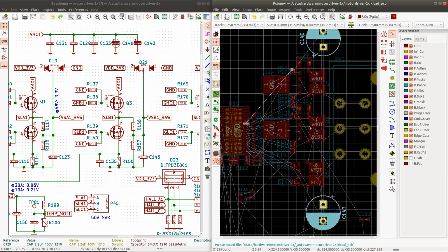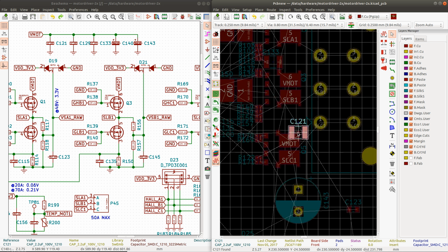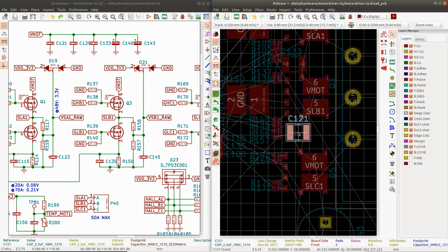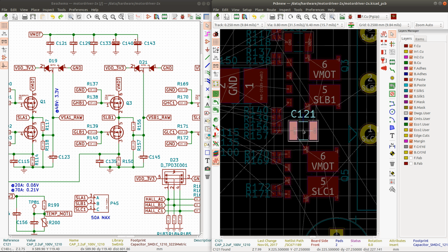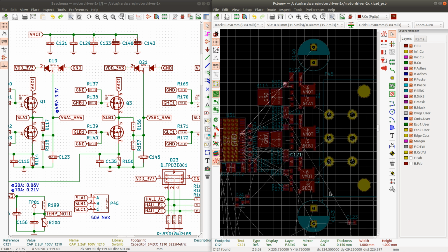So I got the third one here, actually. The third one needs to go to the third MOSFET. Using the capacitors like this, the ceramic capacitors, decreases the series resistance. So we get kind of the benefit of both worlds. When we have an electrolytic capacitor, it has a high series resistance. When we combine it with a ceramic capacitor, we get lower series resistance and slightly higher capacitance.